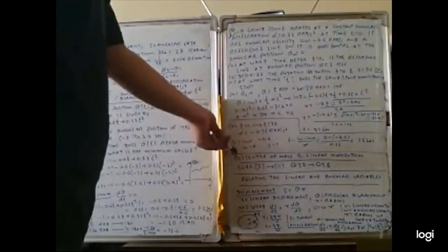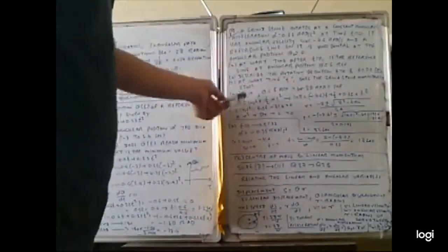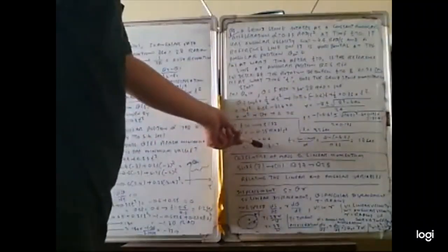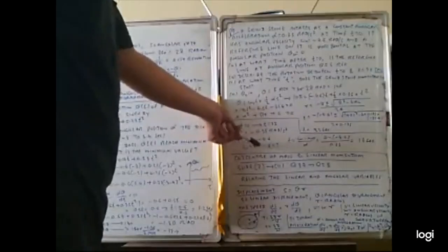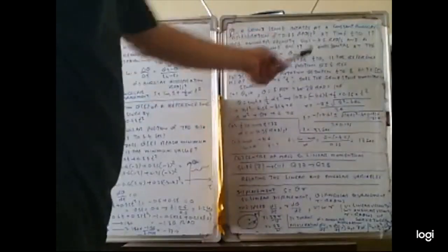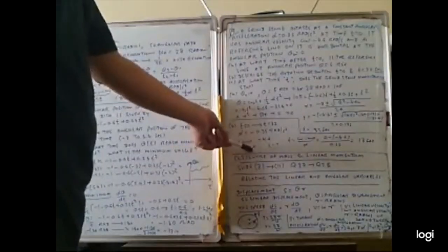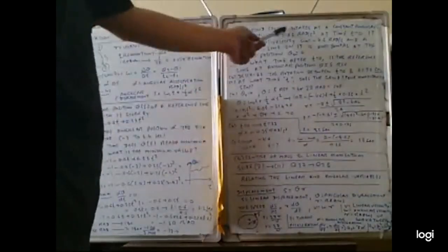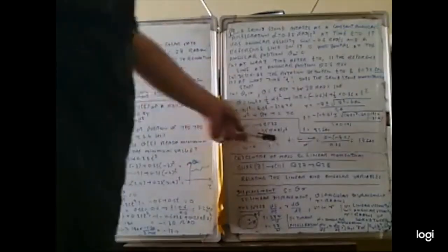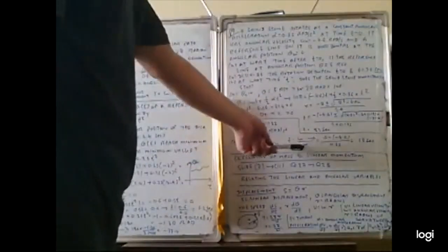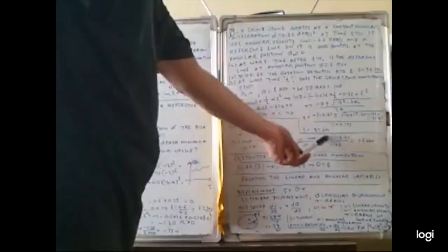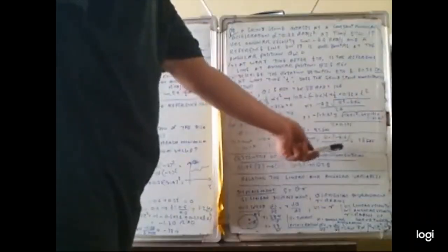And then part C, when does the grindstone momentarily stop? So at that time, omega 0 is minus 4.6 radian per second here, and the final rotation is at 0. So this is final angular velocity 0, so omega equal to 0. We have to calculate T. In this case, angular acceleration is 0.35 radian per second squared. So we calculate T is equal to omega minus omega 0 divided by alpha. So the final velocity 0 minus minus 4.6, divided by 0.35, gives 13 seconds. So this is the way that we can calculate the grindstone's rotation.